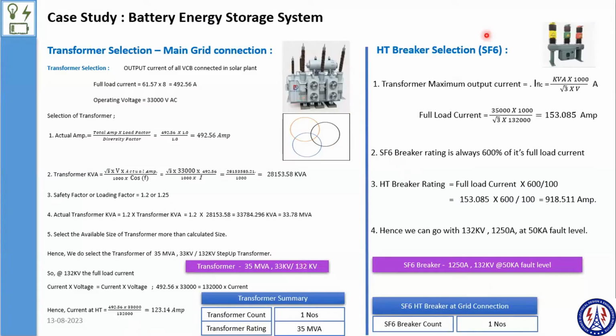Okay. And next to this, there is an SF6 breaker, and you can calculate it based upon a similar principle to what you followed for the VCB there. Here also I mentioned 600, but it's again a similar theory you can approach. For 132 kV, 1250 amps. The same calculation: next to this, what is the current, and then accordingly you can find out its rating.